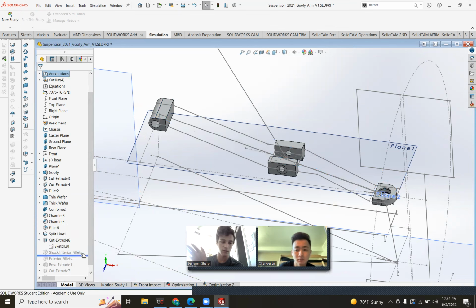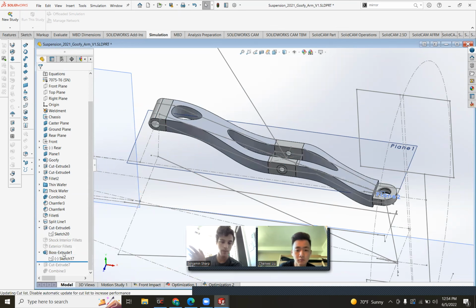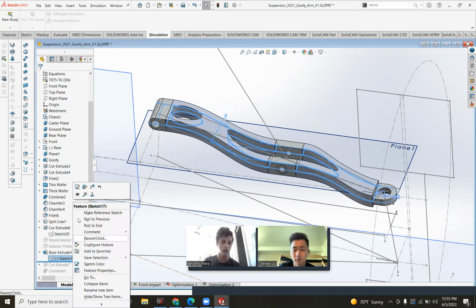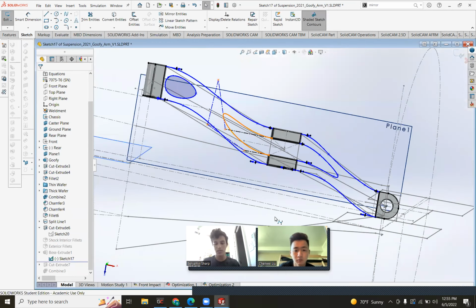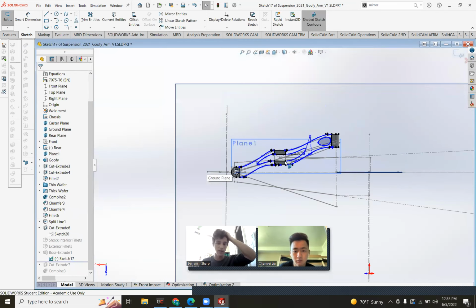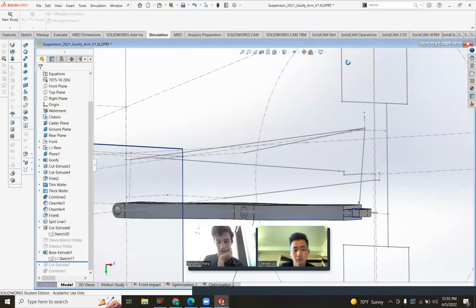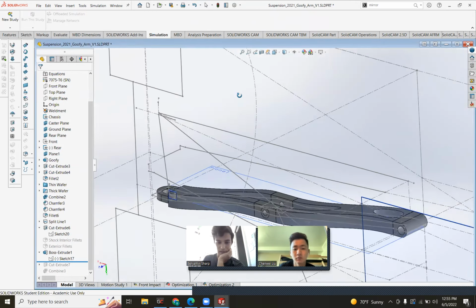And then I brought it all back. I brought it all back by sketching the outline of the resulting optimization FEA, which you know is the blue and yellow elements that are pieced together by SolidWorks. And I just sketched this spline, which is very freehand. Splines are very freehand. They're not very well defined, but they do give you very nice natural looking shapes, which are better for stress concentrations sometimes. And in this case, they are.